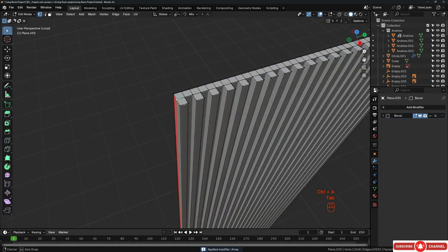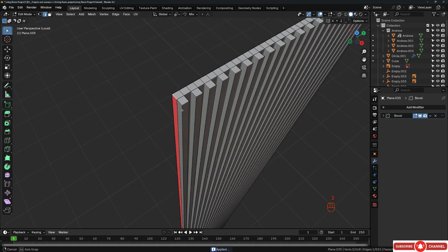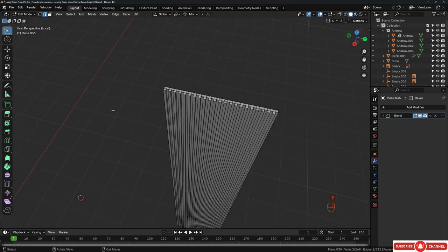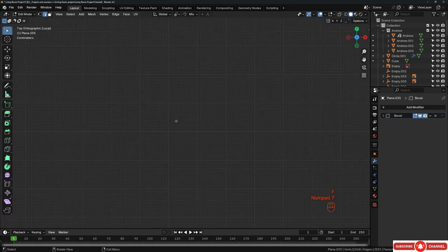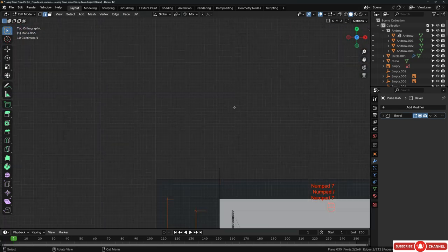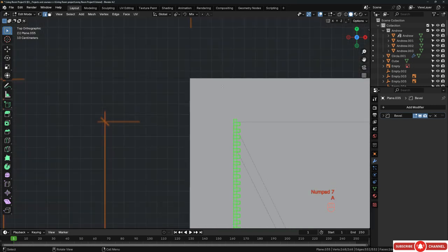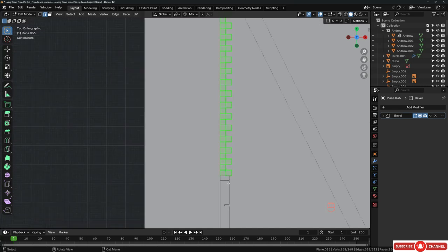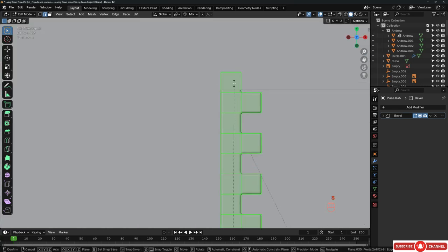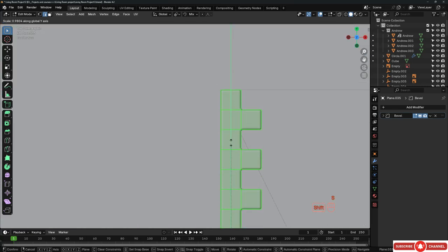And now you can tap and, for example, grab this edge after you switch to the edge selection mode, and then hit F to cap this and cap this area. And it's okay if you go to the top and scale this just a little bit towards the active elements. For example, I can make this edge the active one and scale this a little bit.